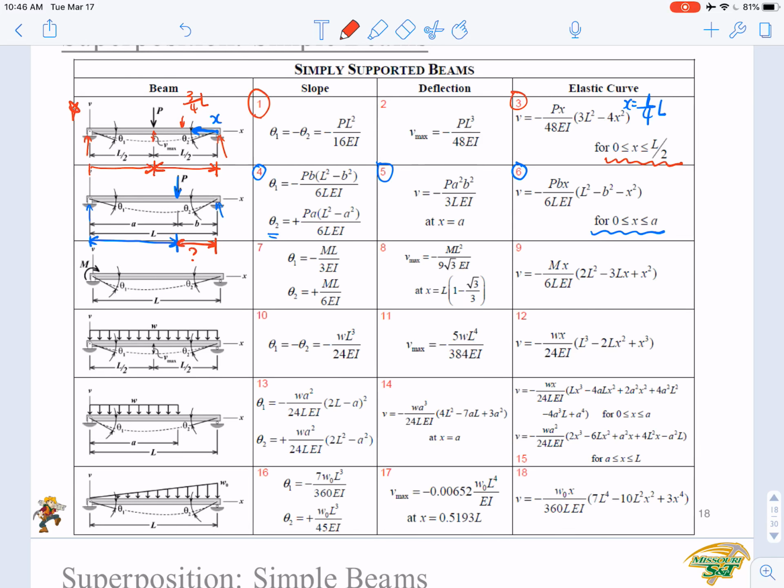So in a similar way, if you want to determine the deflection at a random point in this range, you need to reconsider x, set the origin of x at the right-hand side, with x pointing to the left-hand side. In this way, you can use this equation. Of course, you need to change b to a and a to b. Right? This is how to use these equations flexibly. And other equations are simpler. They look more complicated, but they are actually simpler because they do not have the application range problems.